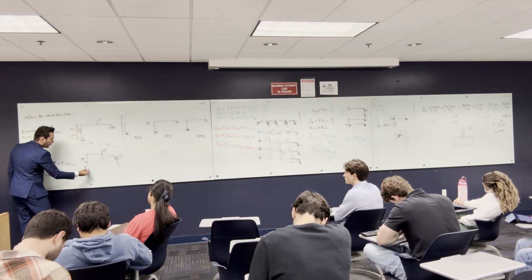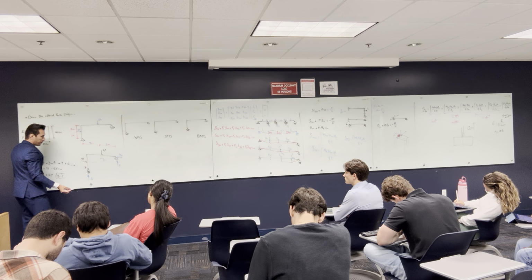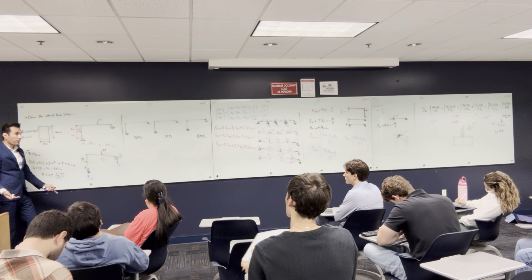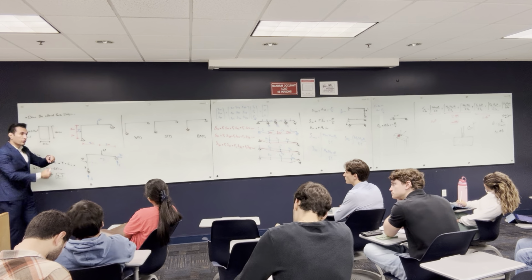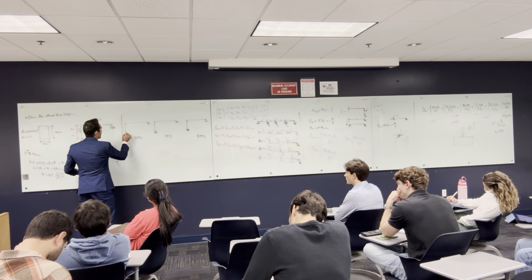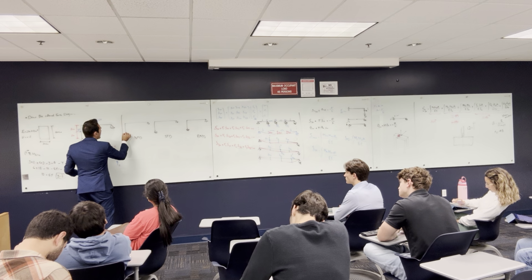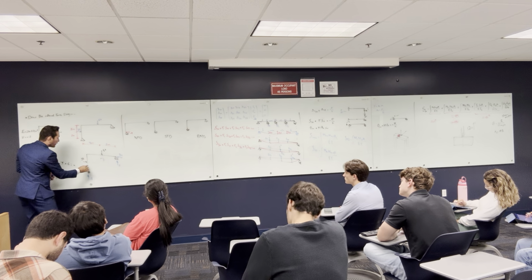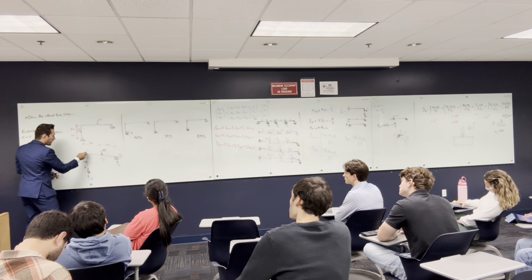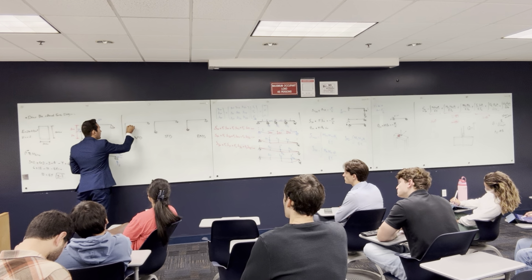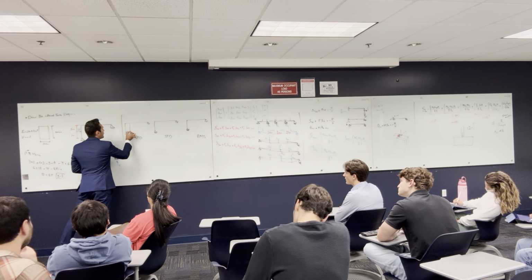Here, what is the normal force here? At this section? 4, positive or negative? It is compression. It's coming to this section, it's compressed at this section. So I have 4 here. So it is negative, so I'm gonna go inside and I'm gonna put negative 4. And the value here is negative 4 until I go up there because there is no force that can change this 4. So this is compression all the way up.